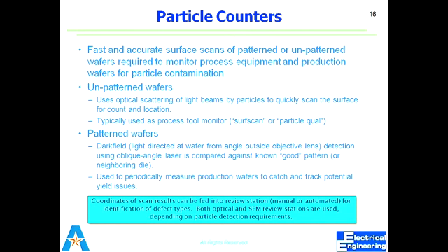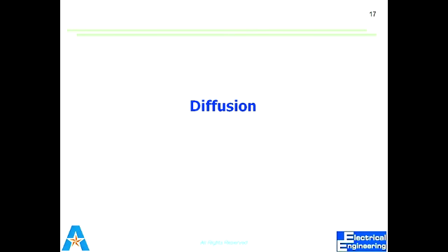After receiving that scattered beam, it compares with an already known scattered beam, to check whether it's the pattern or some other contaminating particle. If there was only the pattern, how it should be, it already has that known pattern in memory. So when it compares with that, if it's scattering the same way, it means it's not a particle, it's actually the pattern. So you strike it at some angle instead of vertically. That is the way we actually calculate the number of particles.